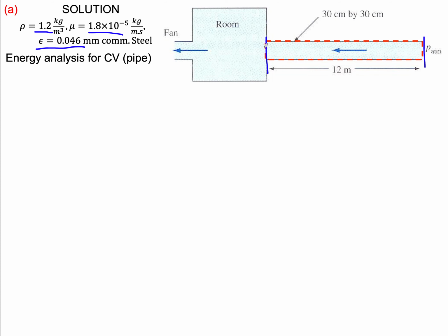And at the outlet, I know that my pressure is 10 pascal, and I don't know the velocity either. But because the duct diameter doesn't vary, mass conservation will give me the velocity coming out to be the same as the velocity entering at the inlet of the pipe.